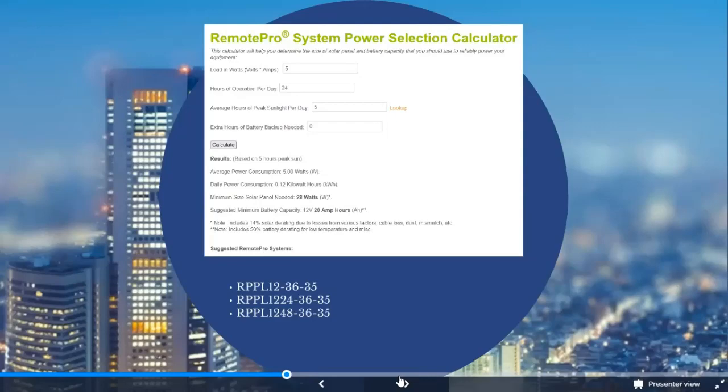For those wondering what typical peak sunlight is, Arizona is going to be similar to this, at 5.5 hours of peak sunlight in winter months. As you go further north, you're obviously going to have quite a bit less. Most places in the US will still have at least 2.5 hours, if not 3.5 hours of peak sunlight for December. But obviously our calculator will show you exactly what each location will have.